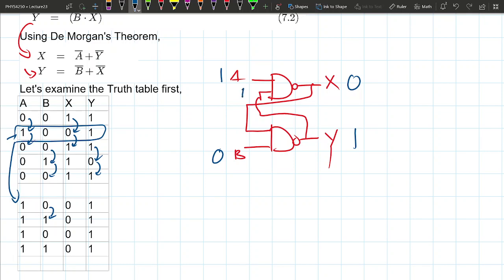Am I doing that right? Yeah. So the NAND between 1, 1 is 0, so that's still valid, right? So now, right, this stays 0, right? So when I switch, remember initially B was 1, right, and Y was 1, right? But when I switch B from 1 to 0, Y still stays 1. 0 to 1, you're right. Okay, I wrote it backward.